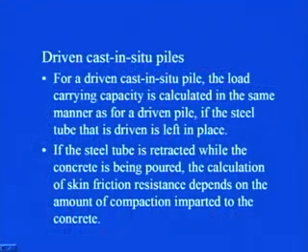If the steel tube is retracted while the concrete is being poured, the calculation of skin friction resistance depends on the amount of compaction imparted to the concrete. So, you see there is a difference between cased and uncased piles while you find out the load carrying capacity in case of driven cast in situ piles. Let us try to see what are the other aspects related to this.